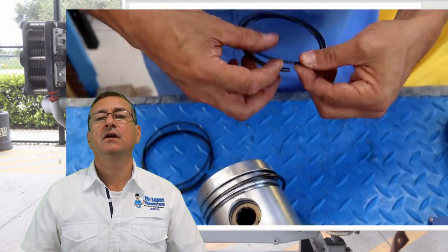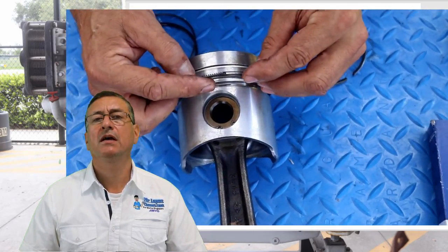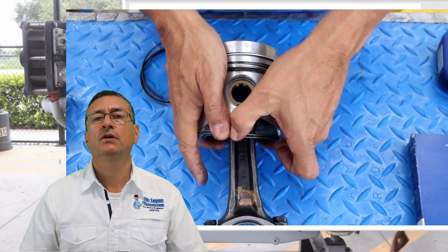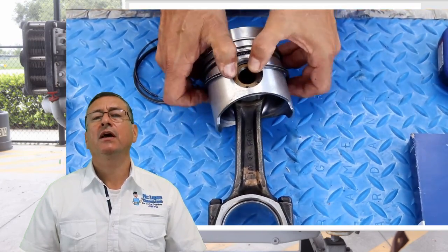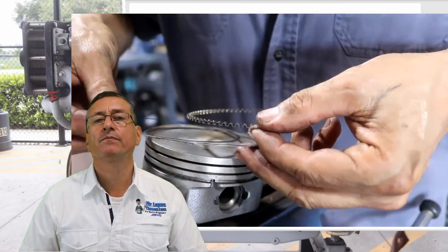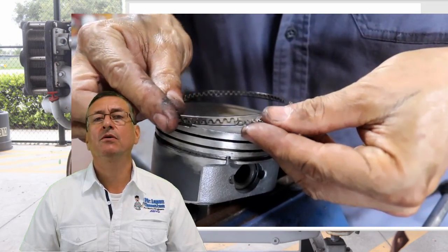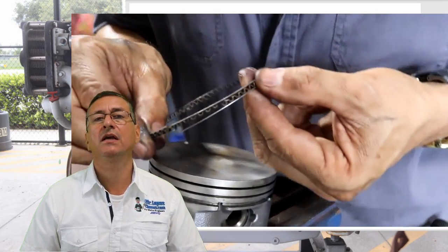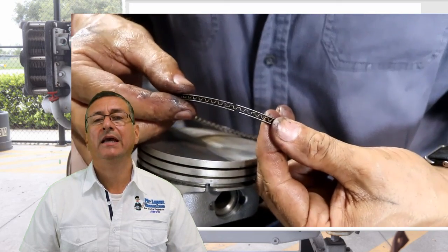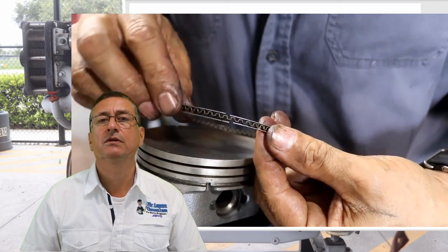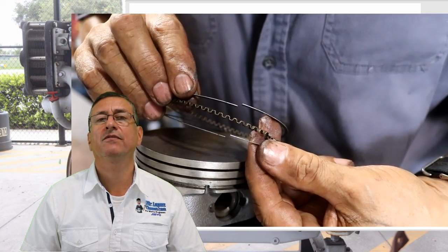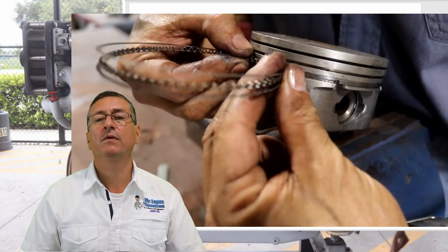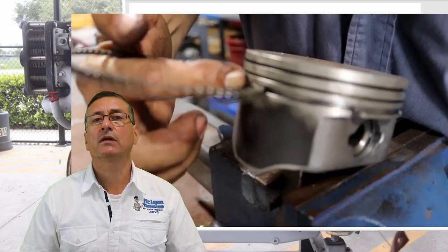The first step is to introduce the spring, and after that, with your fingers, carefully introduce the external element. The other element is like a sandwich: the spring in the middle and two thinner piston rings on each side, like you see at this moment in the video. It's exactly like the sandwich that you have in the video, and those three elements are installed in the third groove of the piston, the oil controller.